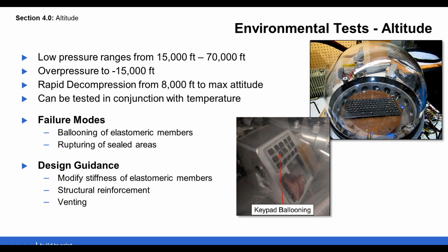This test creates lots of issues when you have sealed compartments and elastomeric members. Keypads can balloon, diaphragms can rupture. If products aren't properly vented or reinforced, any elastomeric parts that require motion are going to have issues.